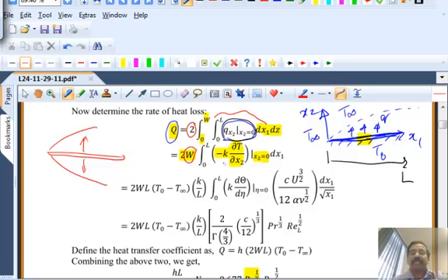Okay, and this flux does change from point to point in the x1 direction. Why does it change? The flux depends on the temperature gradient. The temperature profile is going to be something like this, right? So the gradient at this point is going to change from point to point. So this will be a function of x1. This whole thing will be a function of x1 evaluated at x2 equal to 0. And that integration has to be done properly. Okay. So how do we do that?